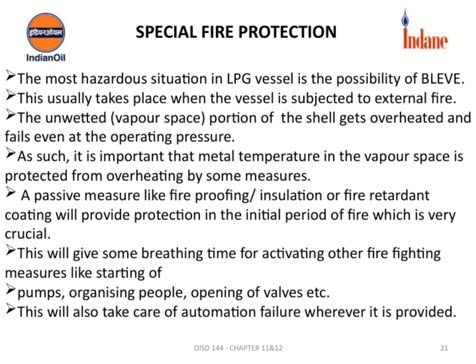Additionally, these passive measures help safeguard automated systems, ensuring that safety mechanisms continue to operate even if manual intervention is delayed. In summary, implementing these fire protection strategies is essential. They buy us critical breathing space, reduce the risk of vessel failure, and help prevent a BLEVE. This is a key aspect of overall safety management for LPG storage and handling.